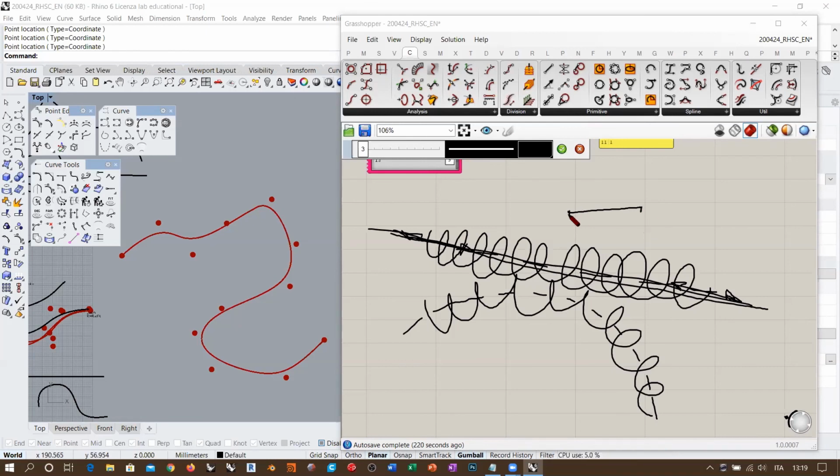So when you need to convert a line, whatever line, into an elastic cord, for example, you must shatter it into segments and provide linear segments. So you cannot work with a NURBS curve. You must take this line and eventually approximate it with a polyline, and each segment of the polyline can become a spring, not the curve. So it's just the way that the elastic problem is translated into an approximation via the ideal springs, okay?